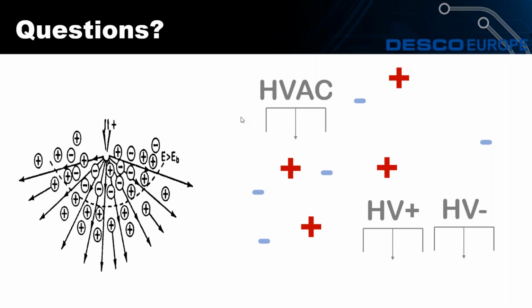One of the controlling factors is not so much what you're trying to neutralize, but what you're trying to protect. So if you have a highly sensitive device on the workbench, really steady state DC, which is going to have the lowest offset voltage of any of the technologies, is the solution that you want to head for. But as Vaughan said, everything is controlled by the standard. So anything that's going to meet the requirements of the standard would be acceptable to the standard. And then it becomes about, do you need something ahead of that, something further than that, depending on the susceptibility of your device.